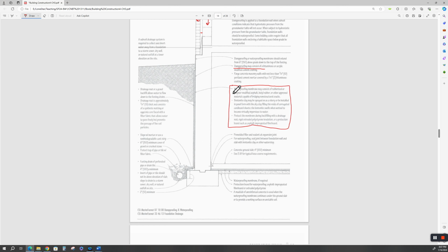So what are you trying to waterproof? How much hydraulic head? How much water pressure? Okay. Some people, he talks about gravel backfill. That may or may not work for you. The problem with gravel with certain soils is eventually the granular material mixes with the soil and you lose your French drain. If you're going to do a French drain, you need to have a geofabric around the whole French drain so the soil doesn't contaminate the granular drainage of your French drain.